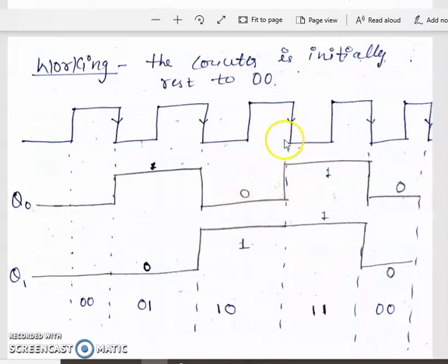So the next clock pulse is coming and the output of Q0 goes from 0 to 1. Now the next flip-flop is also enabled or disabled due to this signal, because it becomes the clock for this flip-flop. So this is positive edge triggering, so the output has no change, it will be as it was before. Okay, so 0 to 1, here it was 1, so the output remains as Q and that is no change. If it is 1, it stays 1. Next 1 to 0, because it toggles for every clock pulse. The 1 to 0 is negative edge triggering, so here also there is a change, from 1